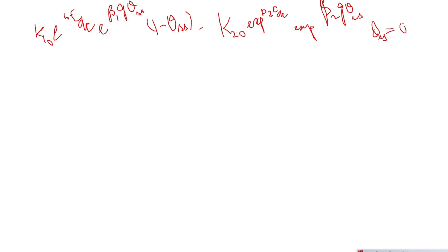So in the previous case, what you do is you will equate this to 0. So you can expect some numerical problem based on this also. You're supposed to find out the theta SS. There can be some possible questions like that also. But you cannot equate it and directly find a value for theta SS. Why? Because you have an exponential raised to that in the denominator also. So separation of theta SS might not be possible. You can put different values of theta SS and check for what value of theta SS the entire equation becomes equal to 0.